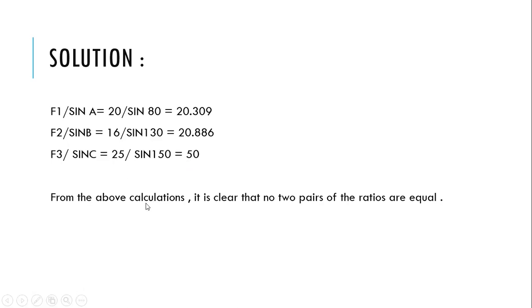Now, from this result, what is the inference? It is clearly shown that the force ratios are not equal. So F1, F2, F3 ratios are not equal, and they are not in equilibrium. They are considered to be non-collinear, non-coplanar forces.